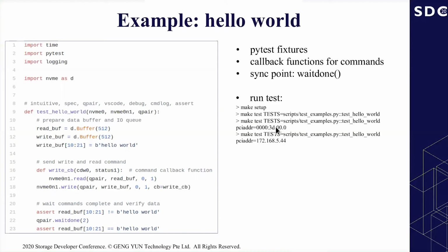We can also specify the BDF address of the PCIe SSD in the parameter PCIe ADDR. We can run tests on multiple devices at the same time with multiple command line sessions and different PCIe BDF addresses. We also support tests on NVMe TCP targets by providing its TCP address.